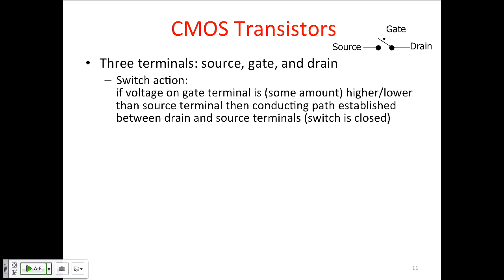They're actually really the same. By convention, one's called the source and one's called the drain. Physically, they're the same thing. It's just which one is connected closer to the power supply that determines whether you call it the source or the drain. And then there's the gate, which is the terminal that controls the switch. Okay. So in a regular transistor, this is a circuit symbol for it.